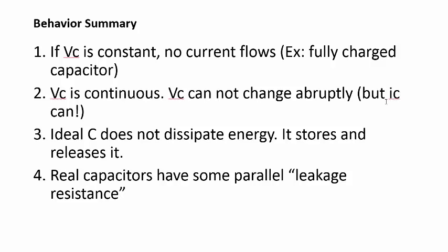For example, if I have a fully charged capacitor, and it's not doing anything, it's sitting there as a fully charged capacitor, and I suddenly connect something to it, that capacitor will discharge into that load, and the current can initially be extremely high. So we've gone from zero current to instantaneously a very high amount of current discharging into the circuit. This is what makes capacitors very dangerous in circuits.